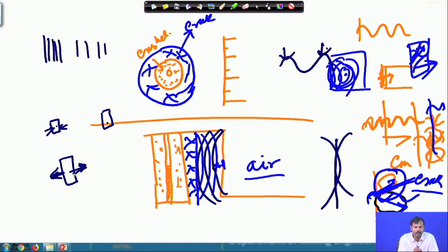So, basically the particle is under a tensile stress at this position. So, what will happen? The tensile strength of the rock is the minimum one, almost 1/7, 1/8, 1/10, 1/12 of the compressive strength. As this portion of rock is being subjected to the tensile stress, long cracks generate here because of the tensile failure. So, these long cracks occur, and this portion will be cracked in a plane.